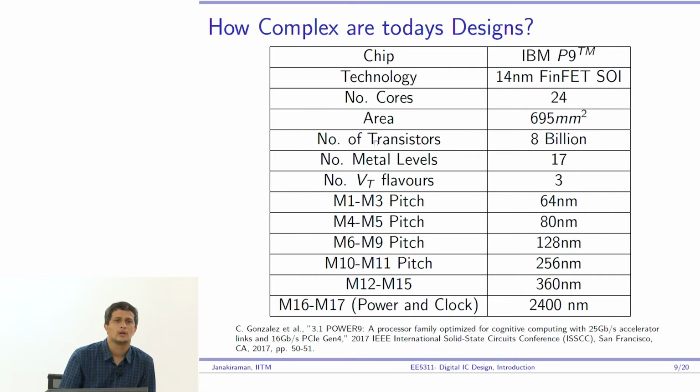Okay, so now if the on current of a transistor is a microamp and the off current, as I told you, is 1000th, right, nanoamp, why is the off current even a cause for concern? It's a nanoamp, right? Yeah, you have 8 billion of these transistors leaking a nanoamp each, which means very quickly we are just leaking amperes of current, right? And what does leaking mean?